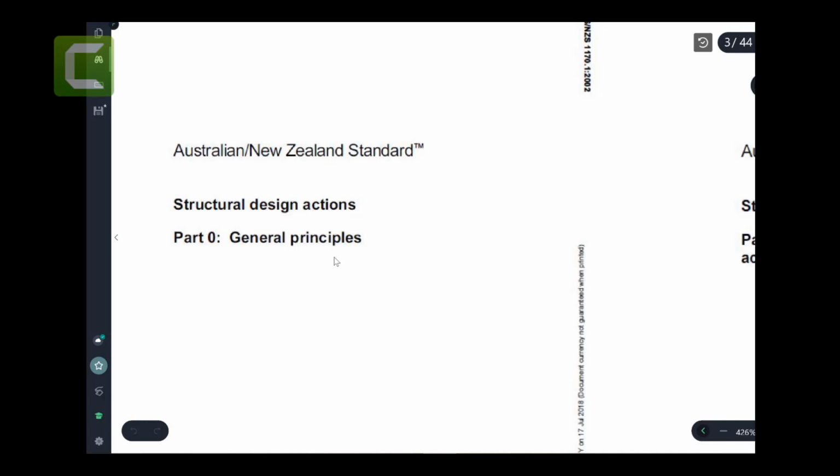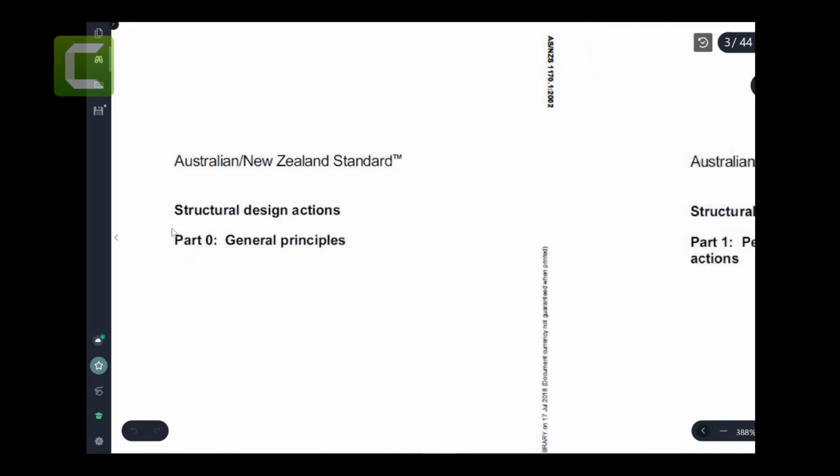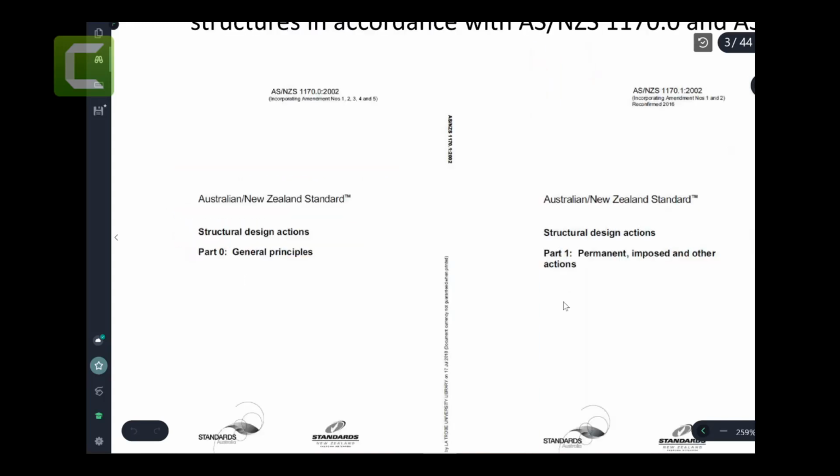I don't want to open the standard, so it does not cost me time, because I want to leave good time for the examples to be demonstrated. So in this standard, the main thing we're going to be mostly using this week is how we mix dead load with live load, and other cases. Like in the coming weeks, we will end up mixing maybe dead load with wind load. But that's really the main reason why we're using this.